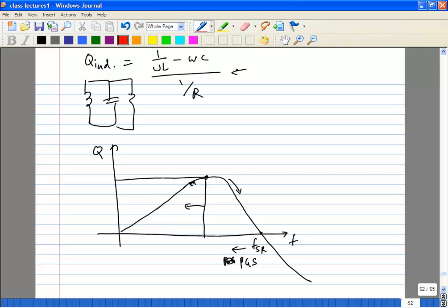Outside the chip, you want to match to 50 ohms because you have come to the domain where microwave effects are very predominant. Inside the chip, your distances are much shorter. You have to burn a lot of power to actually drive 50 ohms, so you want to try to avoid it if possible.